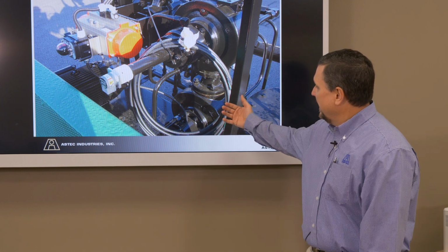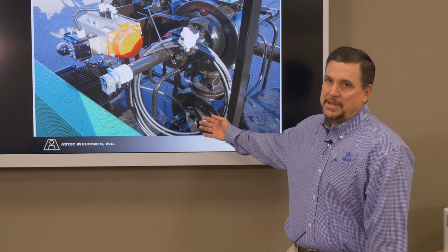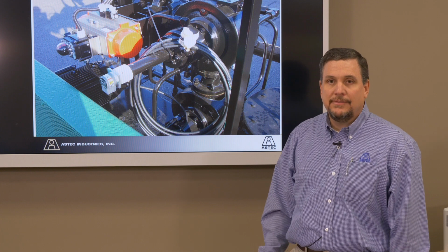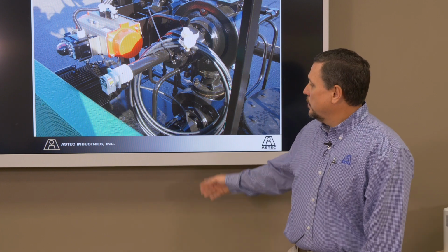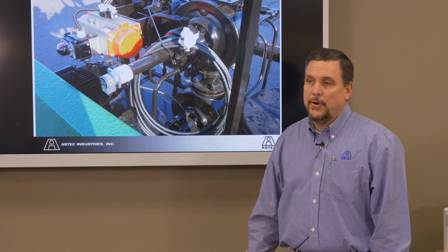They have a plate on the back side that allows one to have a bypass on it. Your pushing pump will always have the bypass. Your metering pump will not. It'll have a blank flange on the back of it. So that's one way to tell that. Also, your pushing pump's always going to be the one hooked to the motor.